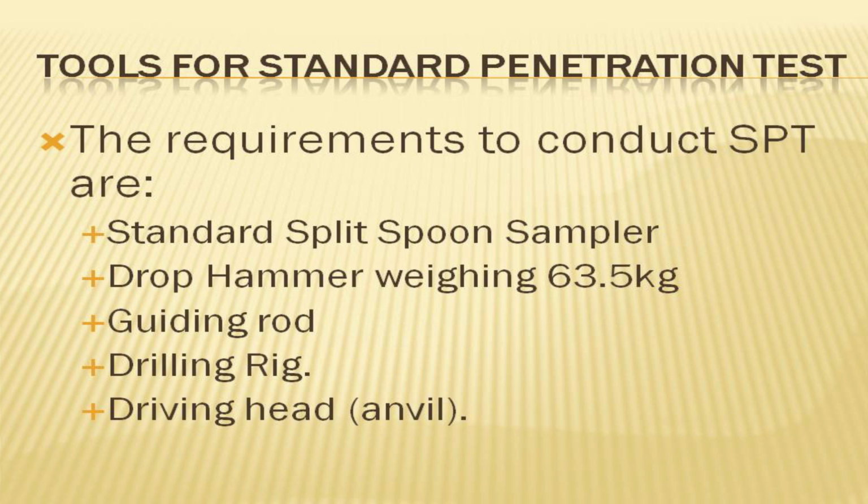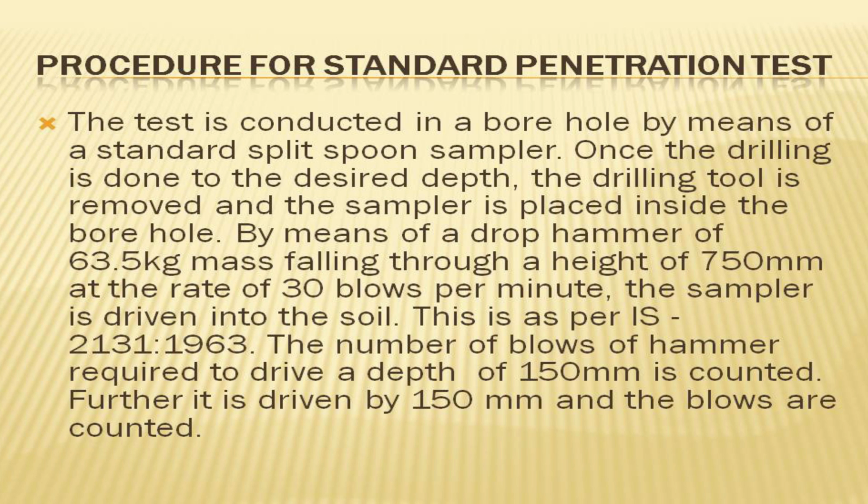Tools for standard penetration test. The requirements to conduct standard penetration test are: standard split spoon sampler, drop hammer weighing 63.5 kg, guiding rod, drilling rig, driving head, anvil. Procedure for standard penetration test.